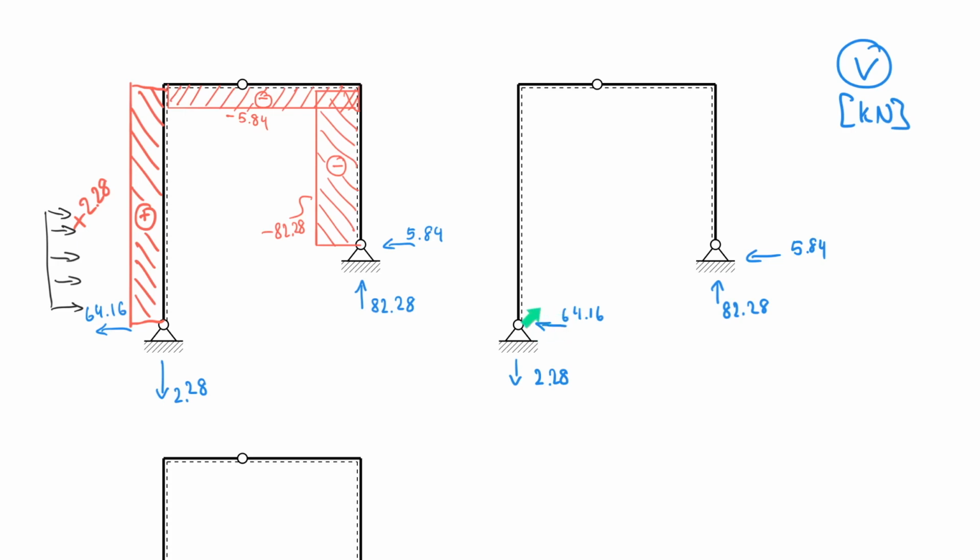But I want you to imagine to actually look at this as being on the bottom, right? So remember what we've done in the past when we had horizontal members. We always said, hey, if the reference fiber is on the bottom, we can start on the left side and then follow our arrows. So that works here as well, because effectively this arrow is under the reference fiber, and so I can just follow that arrow. And remember, there's the evenly distributed force here, so I'm going up, and then I'm going down, down, down, and then nothing happens, nothing happens, nothing happens, and it goes back to 0.